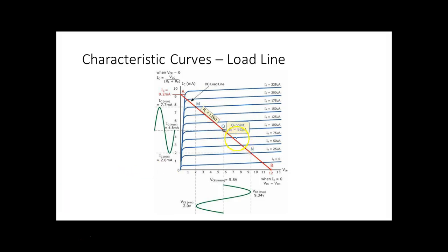Let's say I biased it down here, and then I put the same input waveform, so we would shift it down to here and down to here. Well, what would happen is it would cause the thing to saturate. So my output signal would be clipped on the top, and it would have that when we got up to a certain level. Now, as long as we maintained the level below that, it would amplify fine. But if we tried to put a signal in there too high, then the tops would be clipped.